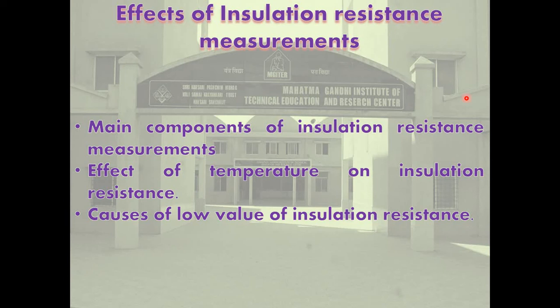For a new oil immersed transformer, the 60-second insulation resistance as a function of the winding temperature and voltage class is given in the table. The value of IR 60 refers to all the windings of the given transformer. Now, minimum permissible insulation resistance IR 60 in megaohm for oil immersed transformer windings.